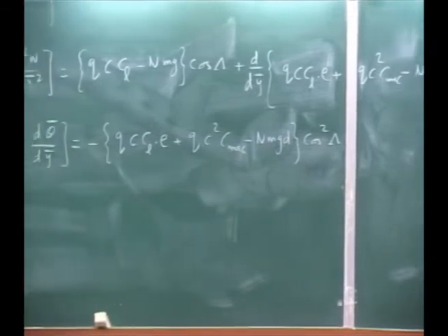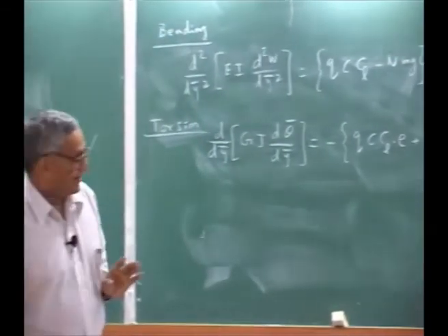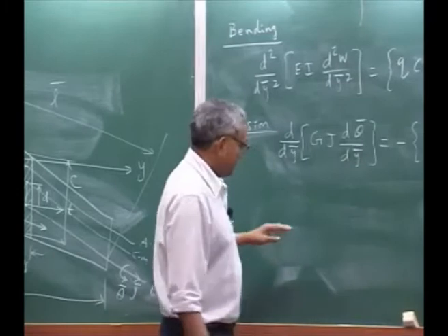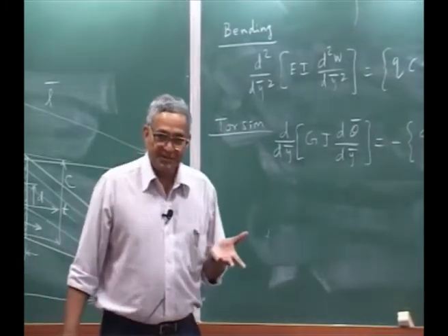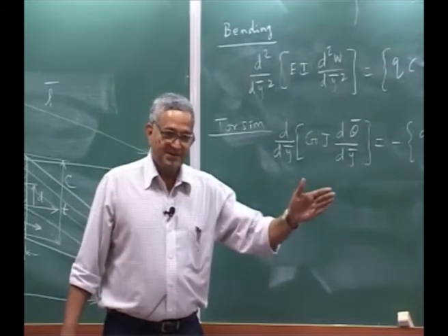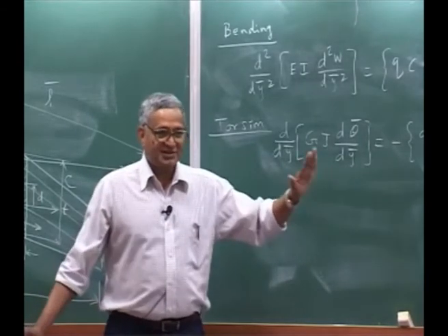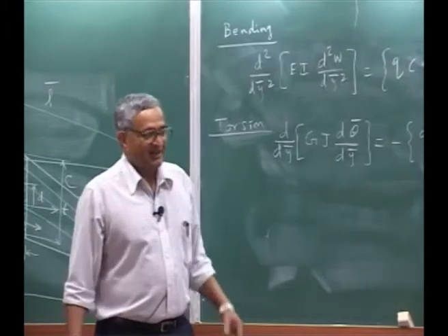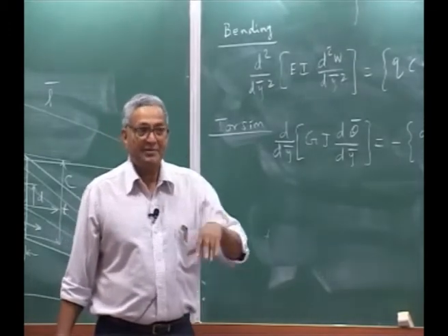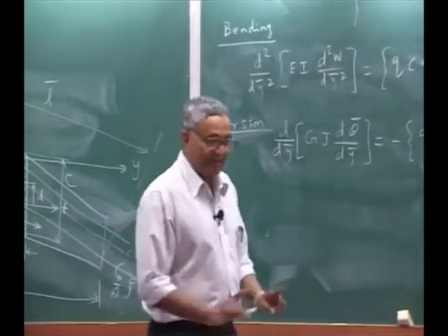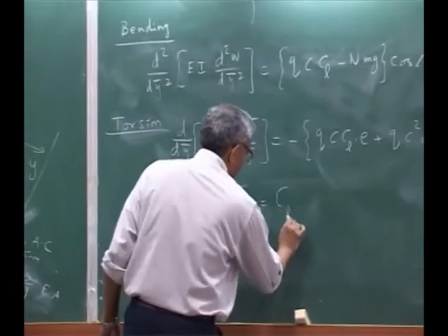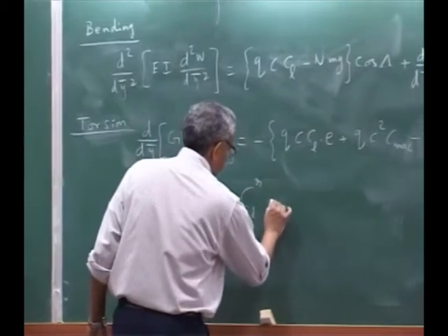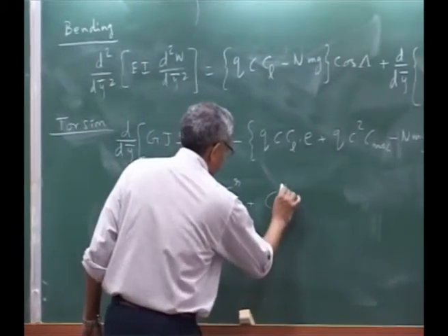That is my lift coefficient. Lift coefficient, if I split it into two parts, that is, one is due to rigid, whatever initial setting angle of attack. Another one is due to the elastic twist. So I am basically splitting my CL as CL rigid plus CL elastic.